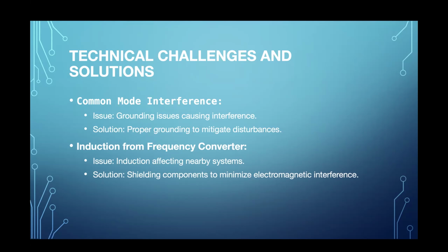So you have high frequencies, and you get many problems even in small wires on the Raspberry Pi. You will have buttons firing all the time. So it's very important to have a very good shielding for all these components. Otherwise, your software will go absolutely crazy, and you don't know why.